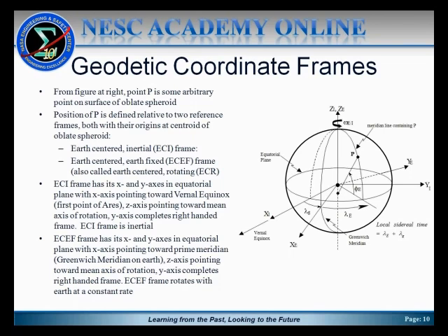As you see, the rotation about the z inertial axis that would orient the meridian containing point P is the sum of the geodetic longitude lambda sub e and what's called the local sidereal time lambda sub g. At any instant, lambda g is just the angle between the direction to the vernal equinox and the direction to the Greenwich meridian, and that angle changes at what is considered to be a constant rate of time as the Earth rotates. That's why it's called sidereal time when it's actually an angle. So the inertial longitude is the sum of sidereal time and geodetic longitude.